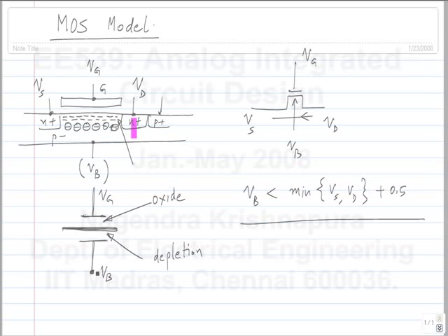When you design something in a low voltage technology, perhaps you can access the bulk, bias it separately. Now, one of the constraints is that typically the substrate of the MOS transistors is common to all the MOS transistors on an IC. So you can't do this, because if you try to lightly forward bias one of the MOSFET junctions by 0.3, maybe something else has become strongly forward biased. But with PMOS you can do this safely. Okay. And also sometimes you have technologies in which both P and N are in separate wells. In that case, you can do the same thing for both of them.